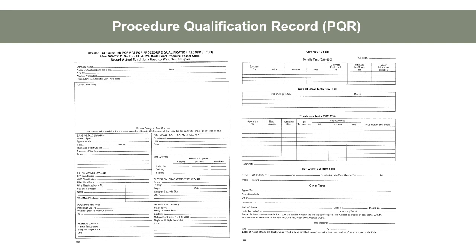You go through here and for ASME Section 9, you address all the essential variables. And if you want to address non-essential variables, you can. You do not need to fill in every blank on here. If you fill in every blank, you're going to get yourself into trouble. If you don't do something, do not put NA, like post-weld heat treatment. Use the word none. If you did not use post-weld heat treatment, put none. Don't put NA. It is applicable, and you just didn't do it. None is better than NA.